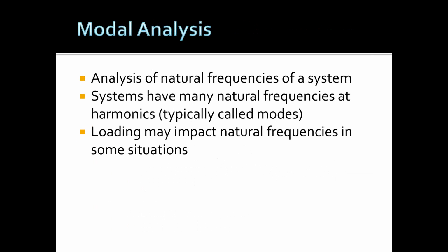With the modal analysis, we're going to be looking at the natural frequencies of a system or a component. Systems will have a lot of different natural frequencies, different harmonics, especially for the various components that are used in it, and those harmonics can highly contribute to the failure of that assembly. You've got to watch out for that. The loading and constraints can impact your natural frequencies in a lot of situations.